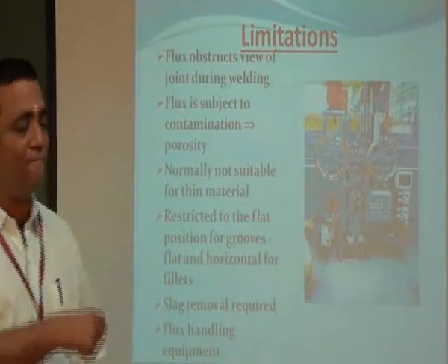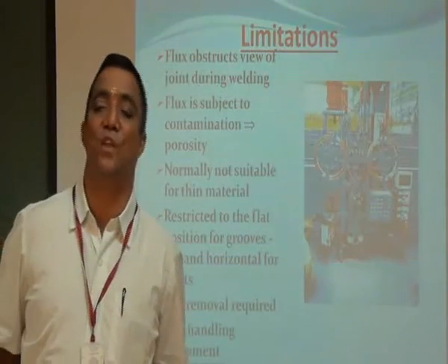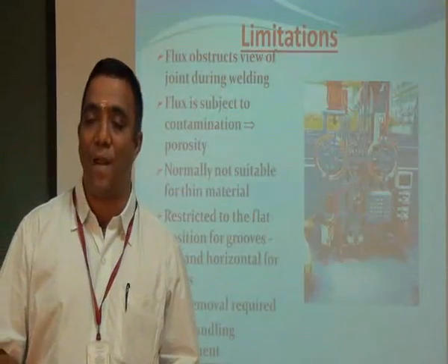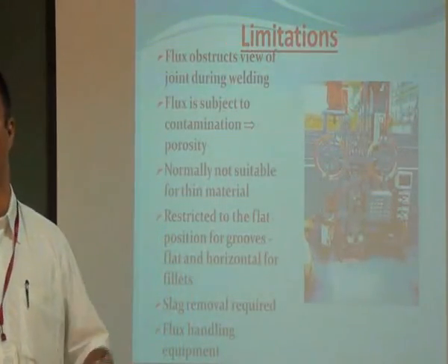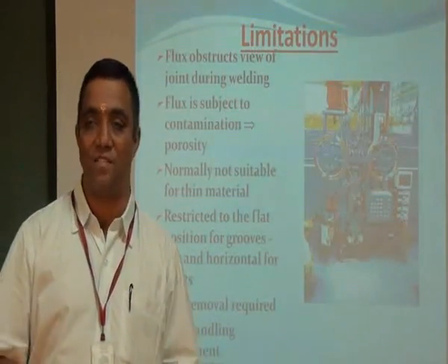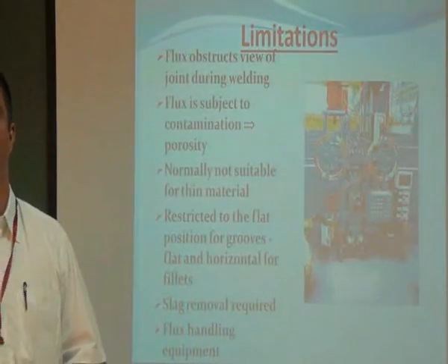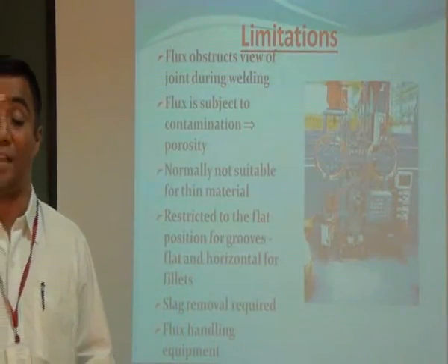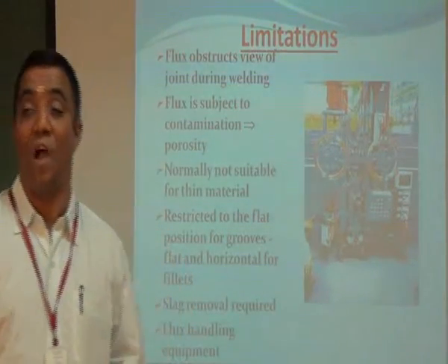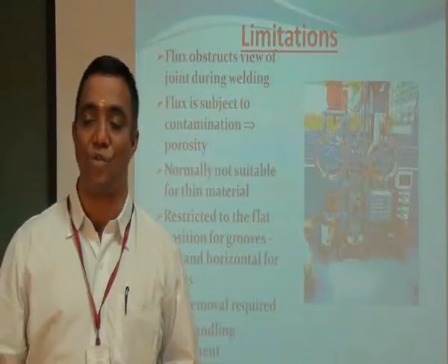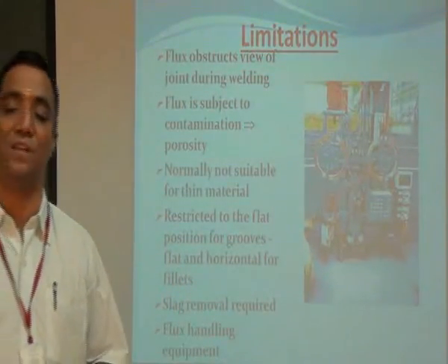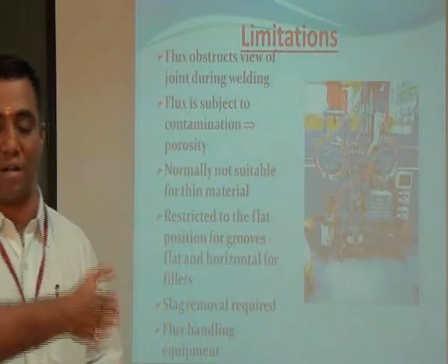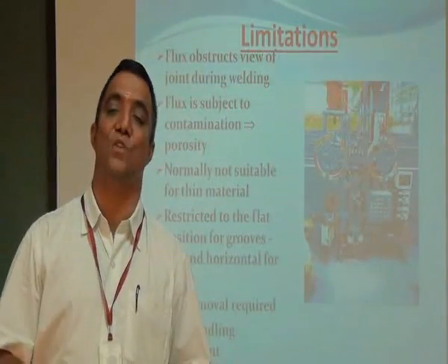So, in general, this submerged arc welding process is a fully automatic process. It can be used for welding thicker plates, with main applications in boiler and pressure vessel manufacture, and single pass welding can be facilitated depending upon the thickness. In the other welding processes we have seen, only a single electrode or wire can be used. But in submerged arc welding, you can use two or three wires, either one after the other or in tandem.